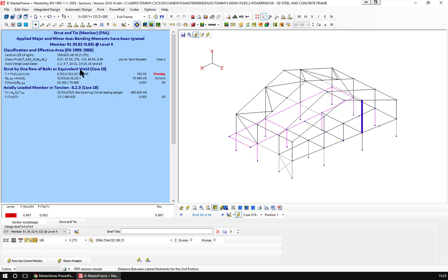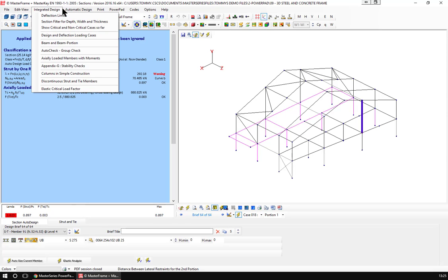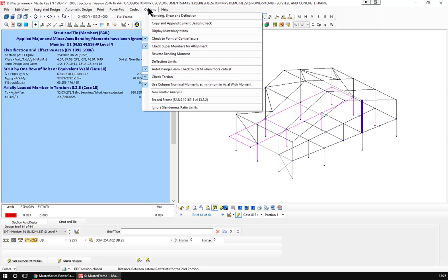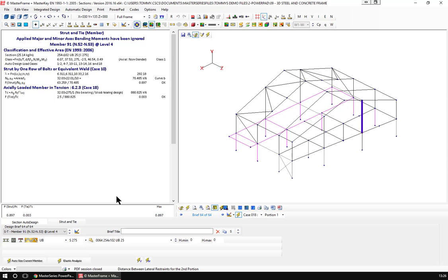It's the lambda, it is the slenderness ratio. Now in the Eurocode and in the more recent BS, you don't really have to worry about the slenderness, so we can ignore slenderness limits because it'll be down to a very low stress that's admissible.